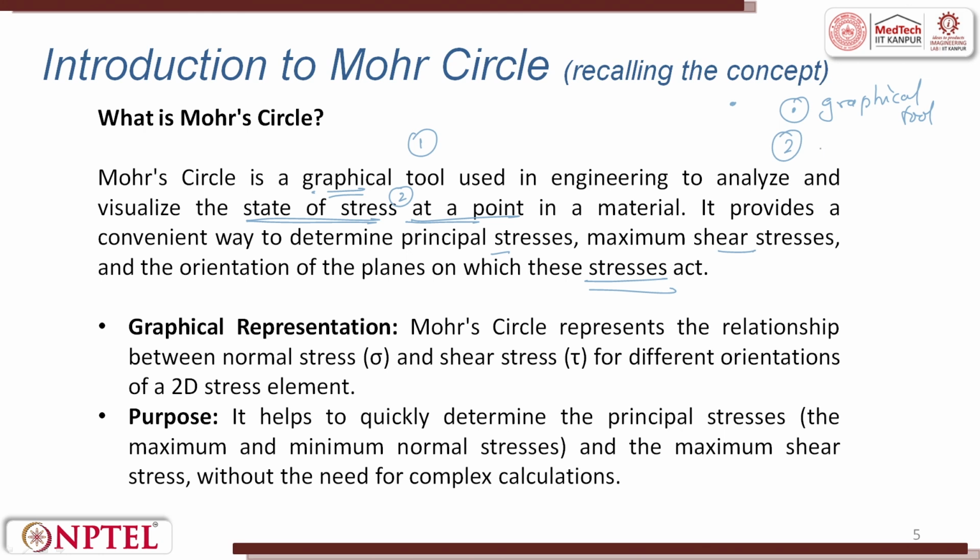Second thing, it tries to find out the state of stress at a point, and then what are you trying to do? It conveniently tries to tell the principal stress or stresses and maximum shear stress. Why is it important? Because this will give us the feeling of what stress is acting on a point, and accordingly we will design or add material, delete material to meet the service condition.